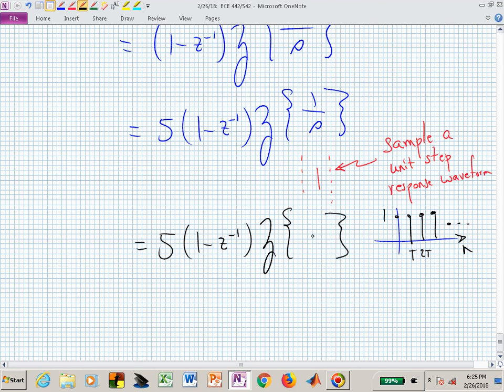What you could do is look at the transform table for exam number 2 in that unit. If I look at row number 3, I'm going to see that in that row I have for the Laplace transform 1 over s. And now I just read across and say, what does that look like? Well, that's now the Z transform of this sequence of numbers, 1, 1, 1, 1, 1. And what was a unit step's Z transform? Do you remember?